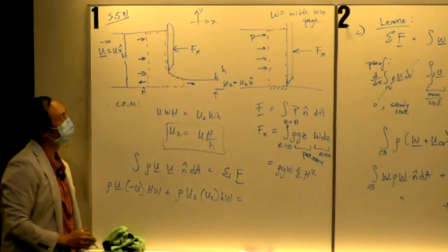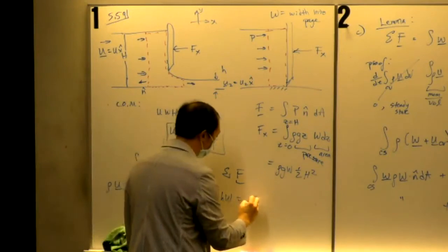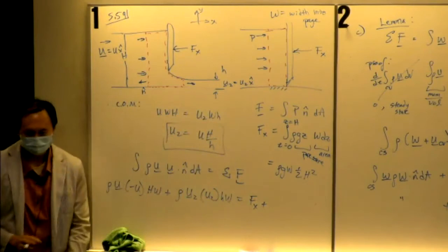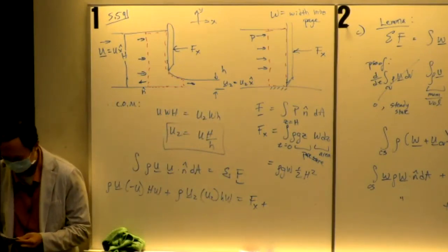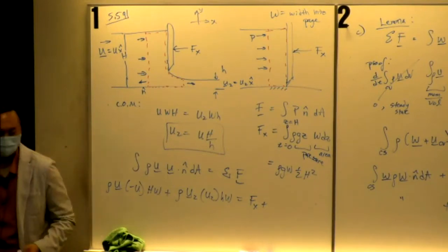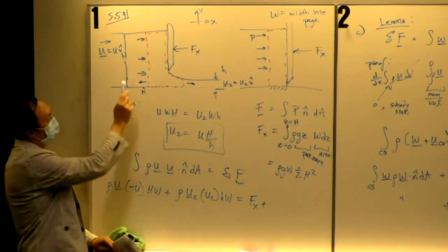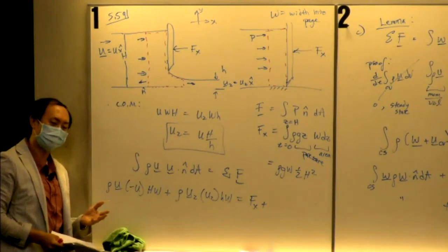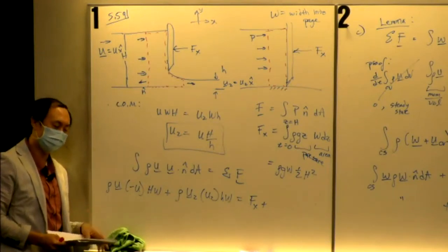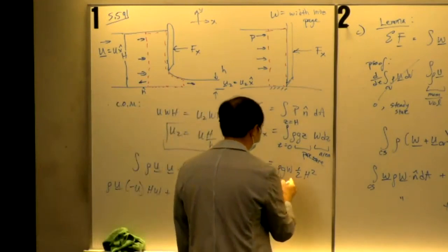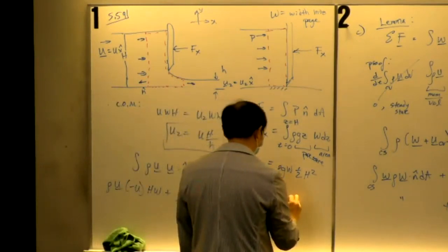And we have the Fx, the anchoring force of the gate, plus what? Yeah, so you still have hydrostatic pressures. Hydrostatic pressures are a funny thing. Even when they're not static, they're still there. So we've solved for up here, rho g w 1/2 H squared.